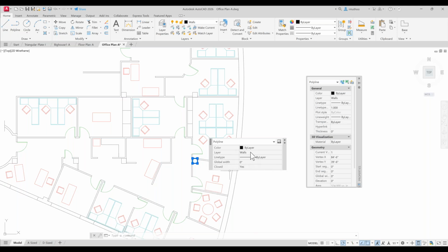Here you can easily go in, for example, if you click on walls, it shows you the layers, and there is a drop down list. You can choose any layer here, and it changes based on that. As you can see, it's showing me the preview of the hatching layer, and then the preview of the HVAC layer. So for now, we'll keep it on walls back again, and that's the quick properties.